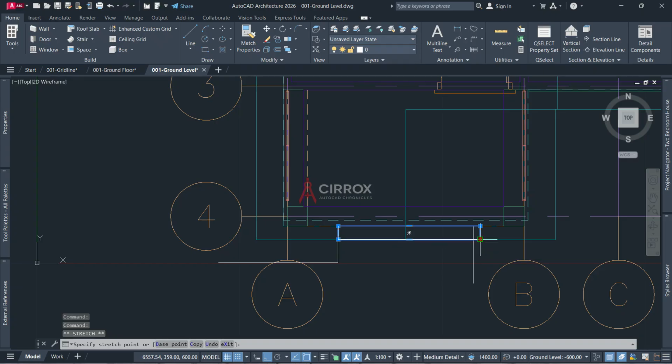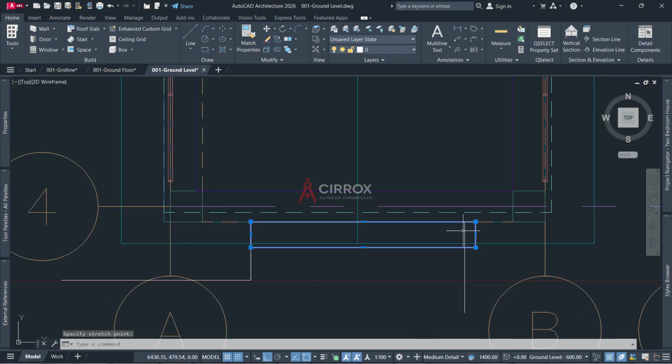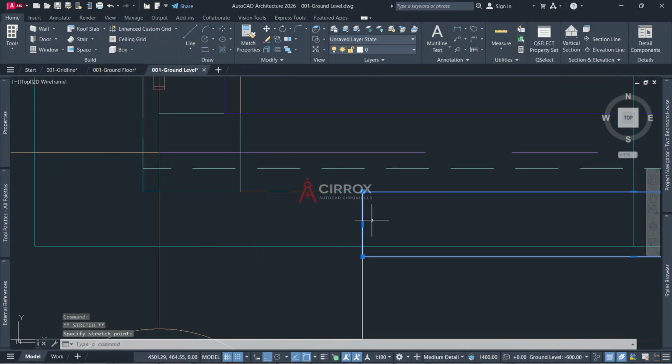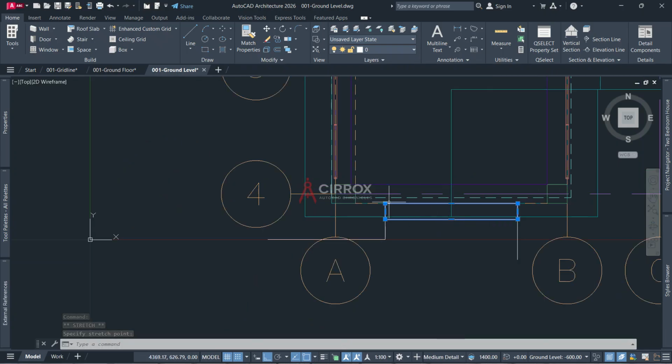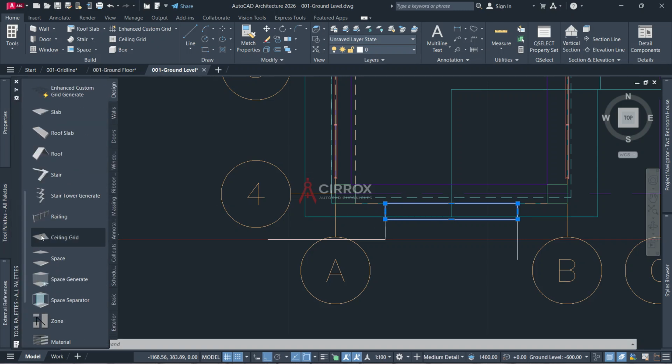It should be somewhere a little bit downward. So this will come here, then this will also come in here. So now I will need to, what's the name? Convert it to a slab, come back to my tool palettes, then scroll down till I find slab.